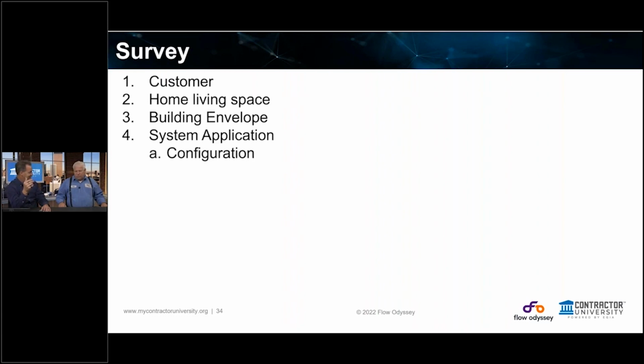I've seen one house I was working on that, in a 10-year period of time, had 7 roofs. So not inexpensive. And the roofer kept saying, I can't find the leak, Eric. I can't find the leak. And I said, well, it's not the roof, dude. It only reveals itself when there's this condition, because the ice is expanding and lifting the roof up and separating shingles.